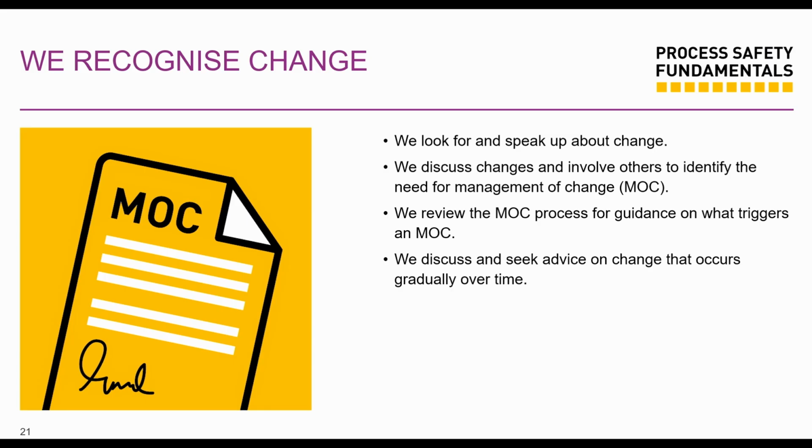If you did a proper MOC, you would have investigated that new chemical you're using, and it would have been caught that this does not work well with our operations. Or let's say you have a block valve installed on a line and you don't properly MOC it, and it doesn't show up on your P&ID, and then you're doing a shutdown activity and you miss that you should isolate or close that block valve, and then you flood the vessel with gas or with H2S. So those are recognized change examples.